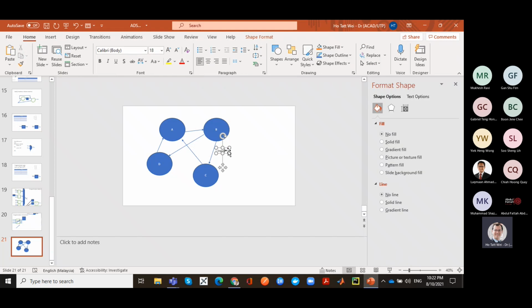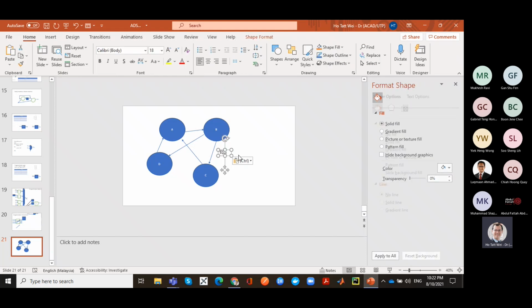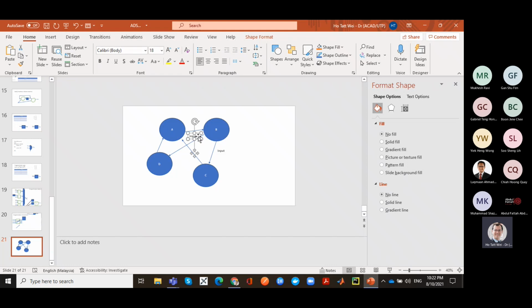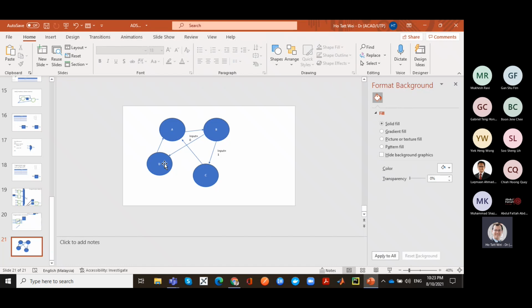So you would have maybe input condition 0, then you go to state D, or input condition 1, you go to state C. And then from D, at the next clock cycle, it goes to A.